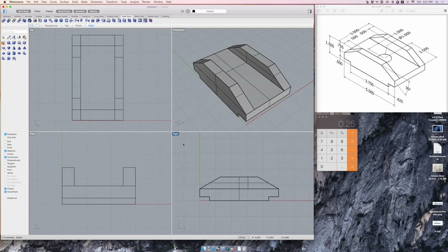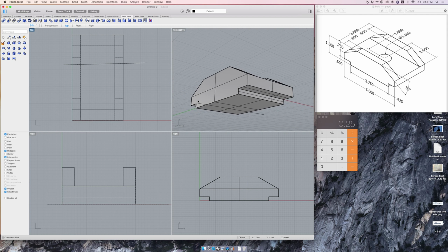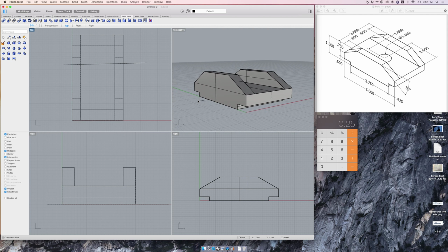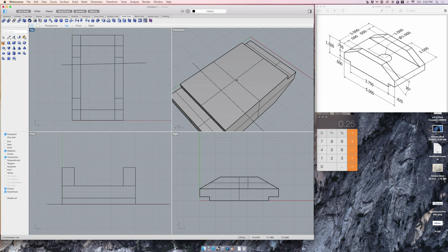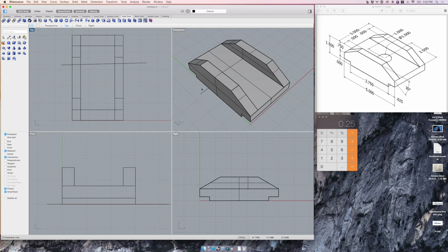And what those allow you to do is, when you're in that particular view, you're drawing on that construction plane. Okay, so it's not moving back and forth closer and farther away. It just so happens that, like I showed, the construction plane that's visible in both top view and perspective view is below our object. So really you've got a couple options. The easy one for this particular model is just flip it over, draw the dang circle on the bottom, and extrude the other direction. But I want to show you how to move your C-planes to make this a little bit easier.